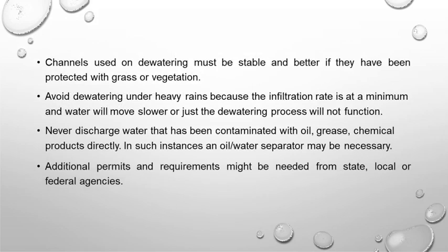Okay, so the important thing is that pumps are used for removing water from excavated trenches. The pumps are used mainly for the following important operations. The first one is removing water from pits, tunnels and other excavations. Next, lowering the water table in excavations, and dewatering of cofferdams.